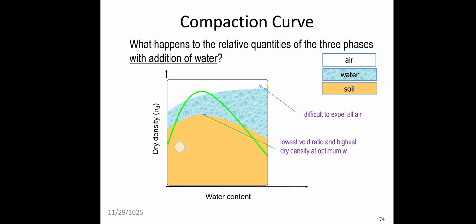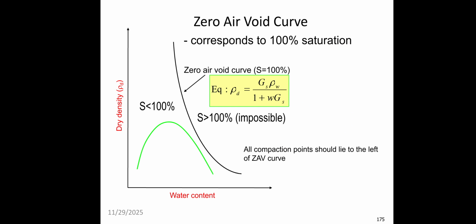As we are adding water initially, here water is less, and density is lower, but here a sufficient amount of water is there, so density has been more. But if you increase the water content beyond that, the contact between one particle and another is lost due to more intrusion of water, so automatically strength has been lost.